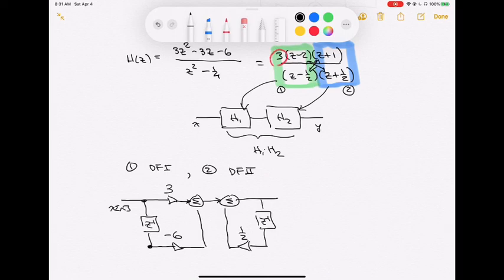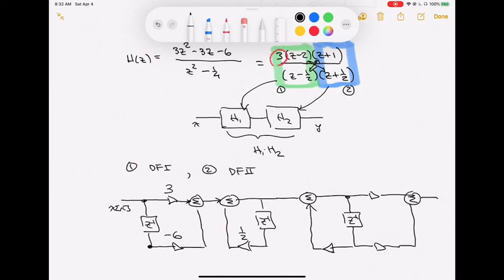That needs to feed into H2, which is going to be direct form 2. What does my direct form 2 look like? Well, direct form 2 ended up coming into a summing node first, and then it was this middle that went down through a chain. It was a canonical structure, so I had that z to the minus 1 coming down. My feedback came first, so I did the poles here first. That was a little bit less desirable, but okay, we're going to do it in this case. And then we had the feed forward part, so we're going to have our 2 coefficients, the B0 and B1 for that second stage, and then that guy's going to come up, get summed in, and out pops, now in this case, my total output y of n.